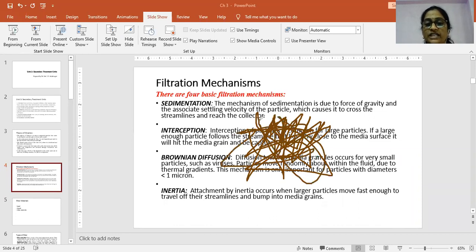Then how can we catch them? Is it possible to catch them in plain sedimentation? Sometimes, even with coagulation and inserting a tube settler or plate settler in the existing design of the sedimentation tank, it is not possible to remove such types of particles. Then how is it possible? In the filter, the sand particles are acting as obstacles and neutralizing the charge of these particles.